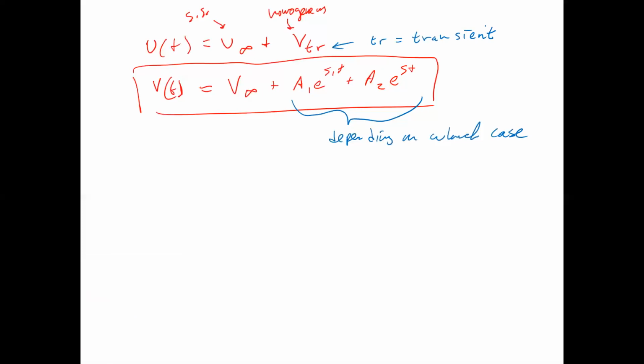So if you're looking at this on an oscilloscope, you have to have the time base set up properly so you can even see the transient, right? Because otherwise, if your time base is too long, you're just going to see the steady state value. The transient will happen so fast. So it dies out rapidly, or it eventually dies out, leaving only the steady state.